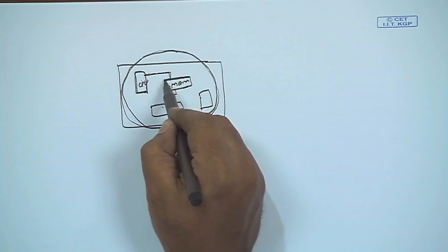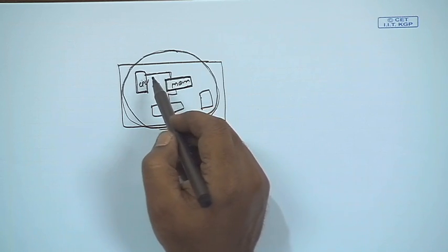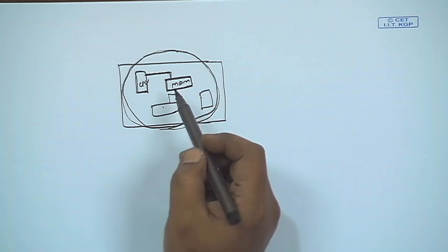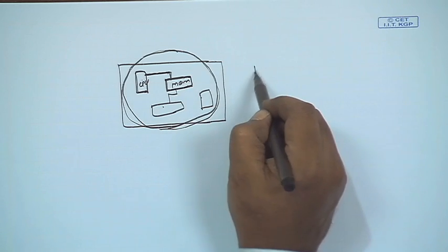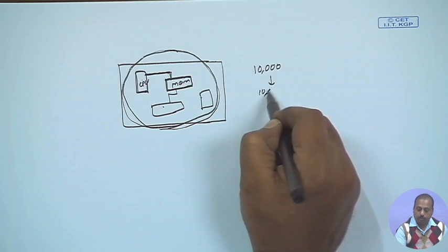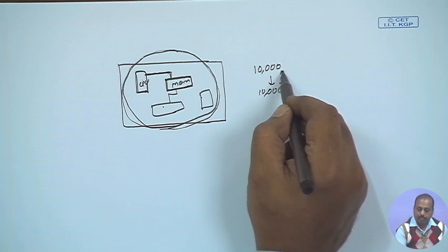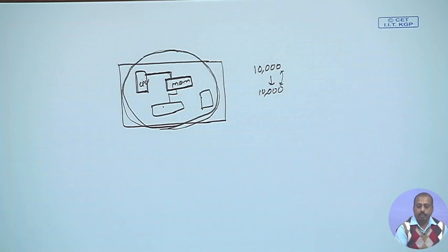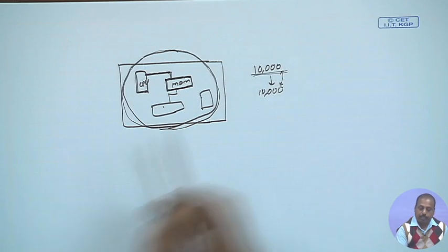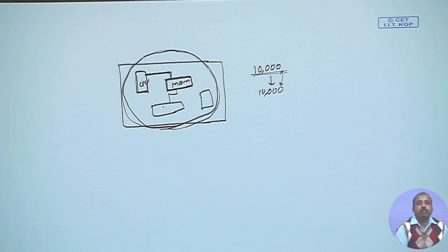So, if I want to test this particular component, then I have to apply some test patterns. Now, how do I apply test patterns? The vendor of this particular core has told me, okay, these are the 10,000 test patterns. If you apply them and find the corresponding 10,000 good responses, and if it is all correct, then you know that my design has been fabricated properly. Now, how to apply these 10,000 patterns? The core vendor cannot tell, because the core vendor does not know in which environment it is going to be put.